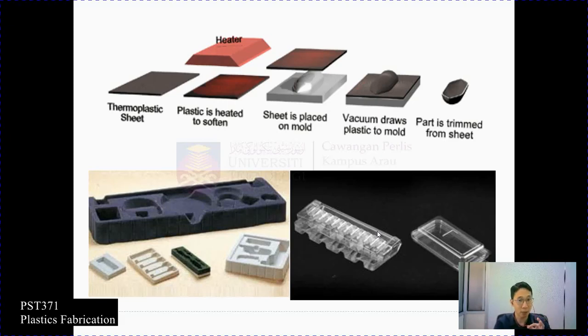When you give a gift chocolate box, that uses thermoforming. Or if you look at a crate of eggs, the egg tray is made from thermoforming techniques, not the paper one, the plastic one. There are also sandwich packs, and usually these types of thermoforming are used for packaging. It can be a clear or opaque material, and most industries use it for packaging, but some high-end industries might use it for automotive parts, or even engineering parts.